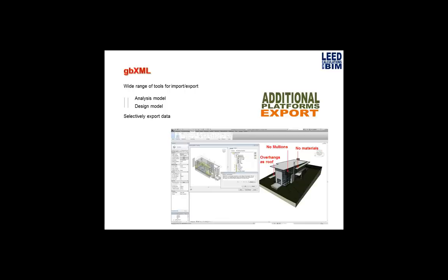It has to stay current, not just with the form, but with where the openings are, where the glazing is, everything. But it's easier to update manually and separately than to stay connected within Revit. It's easier in the long run, because it's a clean export. What are the primary elements? Walls, floors, roofs, openings, and room and space information. Those are pretty much all you'll need to export.